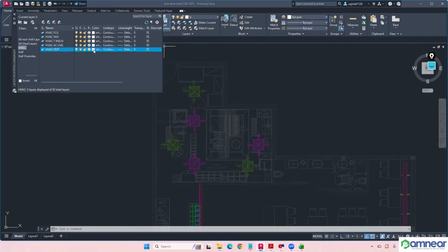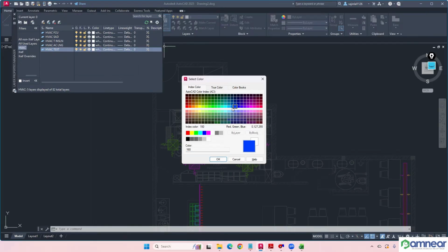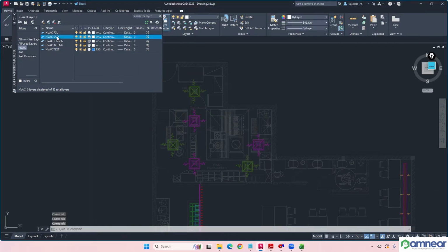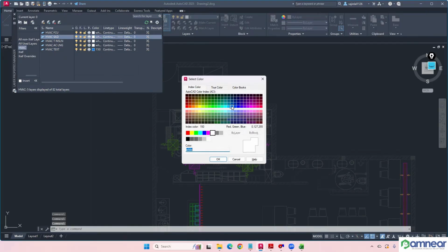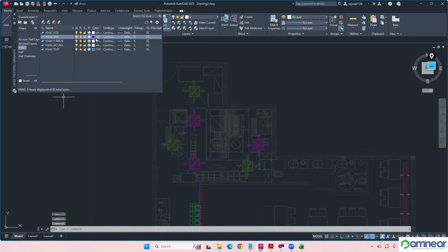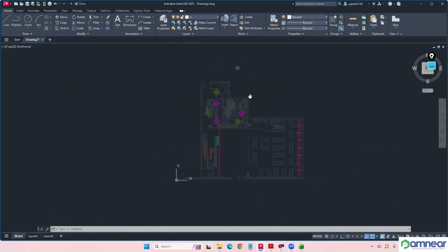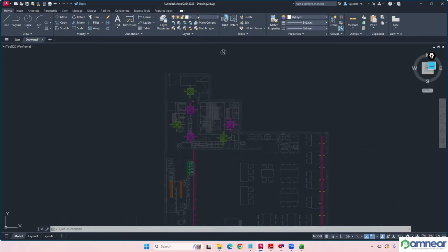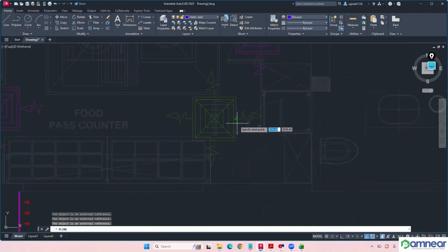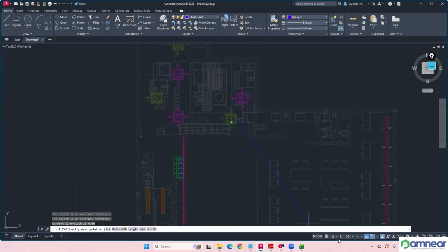So this text color, let me select this one. HVAC SAD color number, for the time being color number 180 we can provide. Okay, and keep it there. I'm just selecting the HVAC SAD layer and making it the current layer. Okay, make current, and I'm selecting a polyline, and through this supply, this is my supply diffuser, I'll be making a line there.